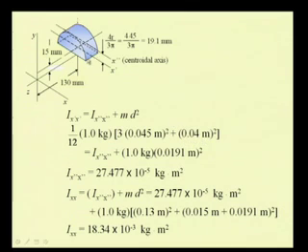So, length is, in this case, 40 mm or this distance. So, we have it as 0.04 meter square. So, this quantity is the second moment of this semi cylindrical feature with respect to this x prime axis, that is equal to I x double prime plus mass times the distance, which is 19.1 mm or 0.0191 meter square.